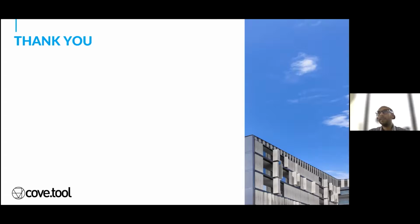...to 6 p.m., you would see the impact on the EUI based on that occupancy. But if the building, let's say it's a lab building or some other use case, is operational 24 hours, the EUI would represent that. But the reason daylighting is not considering 24 hours is because there's no daylighting after 6 p.m. or before 8 a.m. There's not much daylighting, so even if you do have sensors on the building, they will not be adding any more value because there's no daylighting. So there's no more EUI to be offset from that.